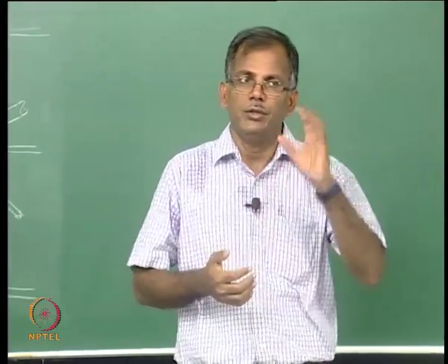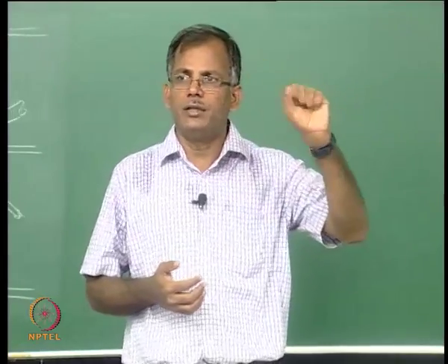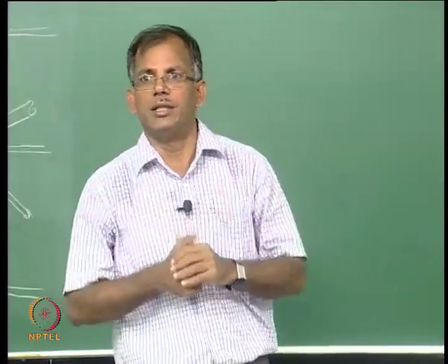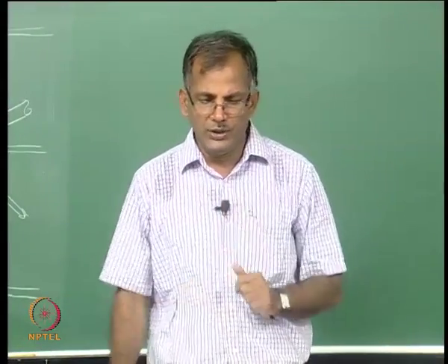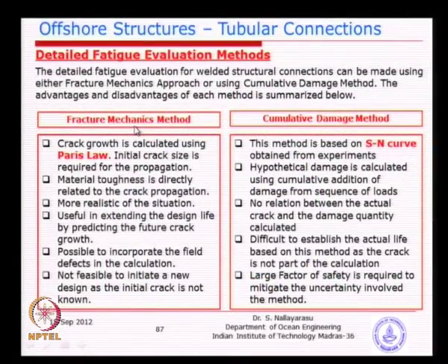That means you have various combinations of cycles and stresses for the same answer, is it not? So, that is why you get a graph something like this. So, we are going to see this fracture mechanics is a starting point where the relationship between the number of cycles and the stresses were related, but unfortunately because of the complexity this method of fracture mechanics was unable to proceed for the detailed design or the initial design, basically because the information is not available.